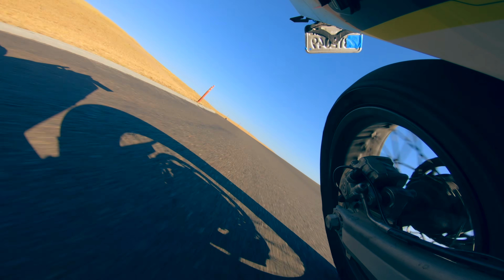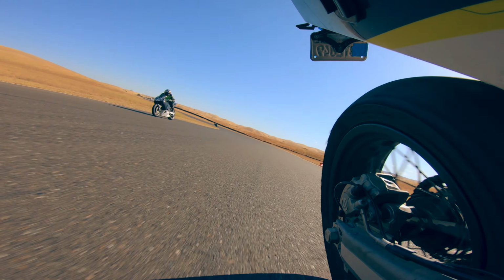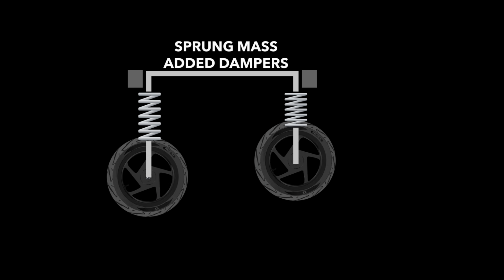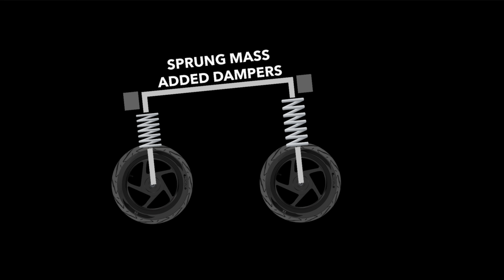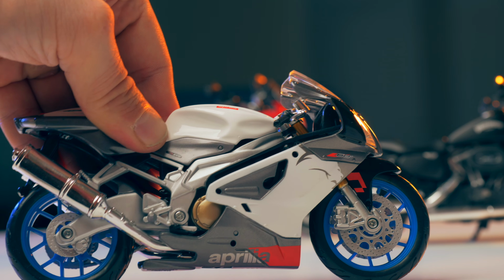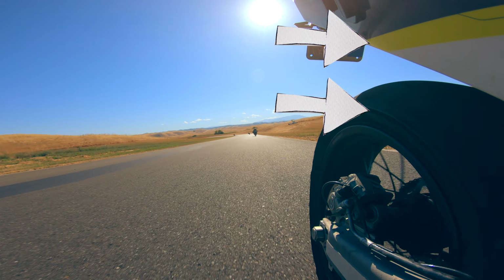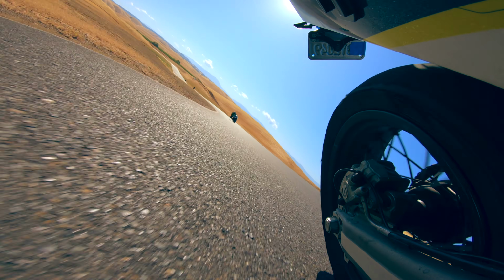So we talked about braking, now what about accelerating? Well, if we're going to talk about accelerating, we need to understand the rear end a bit better. Let's look back at the simplified motorcycle design shown earlier. Let's assume it has a chain drive. When you roll the throttle, our simplified motorcycle will squat or pitch rearward. What does this do to our suspension travel? It diminishes our travel. To solve this problem, we need to introduce anti-squat, or in other words, we need to stop the rear suspension from compressing under acceleration.